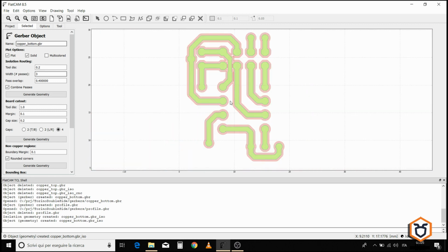Since on our machine the pitch between traces is set to 0.2 mm, it is recommended to set the layout rules of your CAD, the DRC rules, in such a way that do not allow to generate a circuit with space between tracks or track and pad, and so on, less than 0.2 mm. In this way you will be sure that using a bit with the diameter 0.2 mm, you will always get a machining that will produce a working circuit board essentially without short circuit.